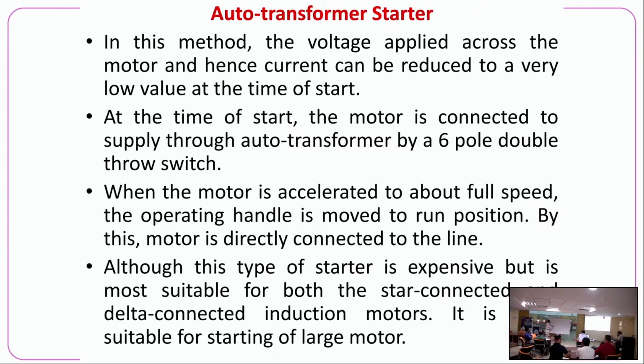So in a variac we can slowly increase the voltage from 0 to rated voltage, so that starting current increases smoothly. There will be no huge inrush of current. So when we apply voltage x times the phase voltage, x is less than 1, obviously x is between 0 and 1.